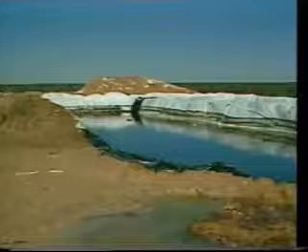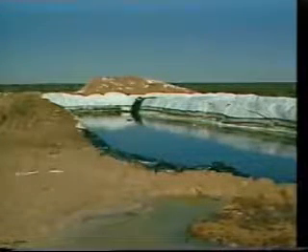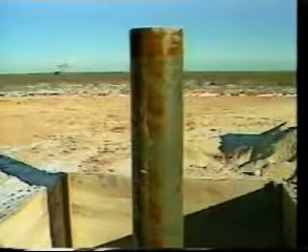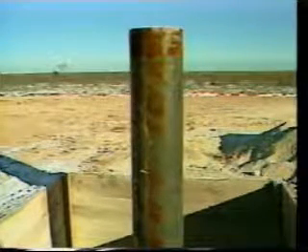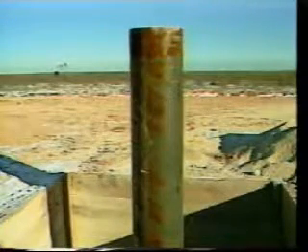The reserve mud pit is excavated and lined with plastic to prevent runoff, and the entire location is surrounded by a drainage ditch. At the staked well location, a cellar is dug to accommodate the components of the surface equipment, which will be below ground level when the well is completed. A conductor hole is started in the center of the cellar and lined with a conductor pipe. This first portion of the hole may be started with a portable spudding rig or by the drilling rig itself.